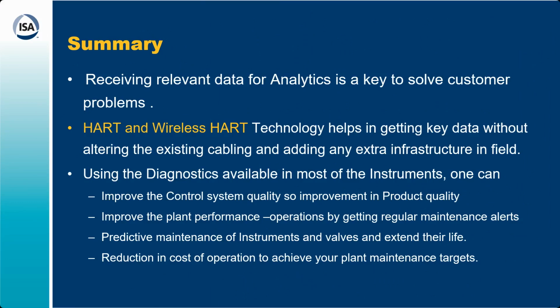So why HART and WirelessHART technology helps in getting data is that it needs no extra cabling, no extra cabling cost, and does not add any extra burden to the existing infrastructure in the plant. So using the diagnostics available in this instrument, one can improve the control system quality as we discussed, so that improvement is there in the process quality. Then you can improve the plant performance and operations by getting regular maintenance alerts. Plus, you can get predictive maintenance of your instruments and valves, especially valves, and extend their valve lives.